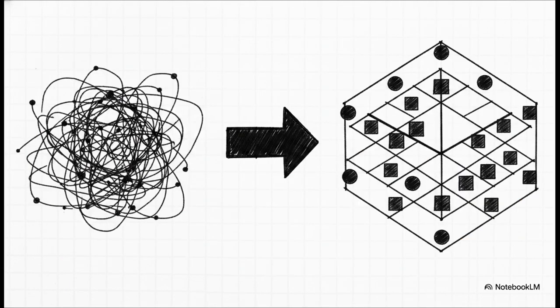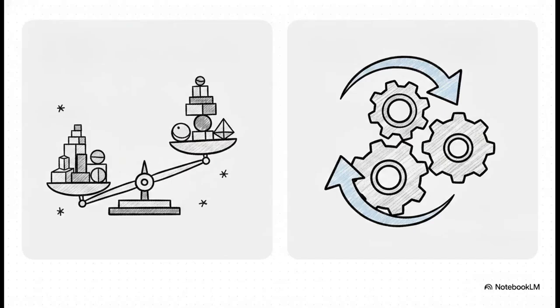And this brilliantly illustrates how we've taken a massive, chaotic diagram full of flashing unknowns and systematically organized it into a highly manageable mathematical model. The physical network collapses into a sparse Ybus matrix. Every single bus is strictly classified as swing, PV, or PQ. And we're left with exactly 2 knowns and 2 unknowns per bus. The mathematical board is now completely set. Let's move forward and see how this builds into our next step.